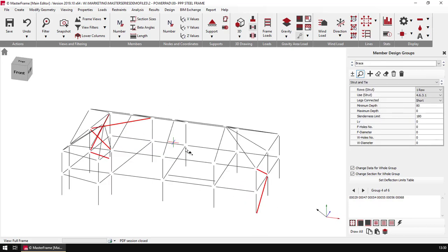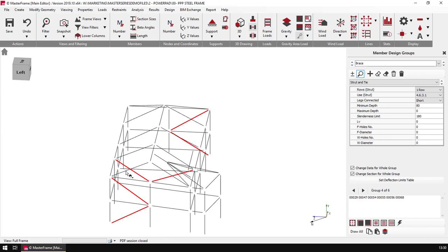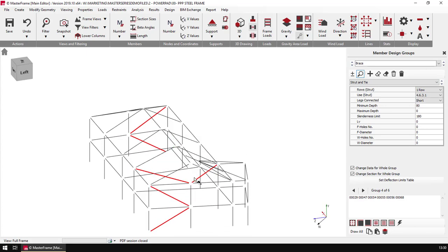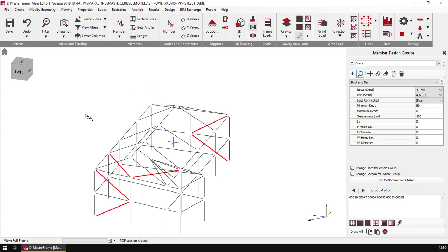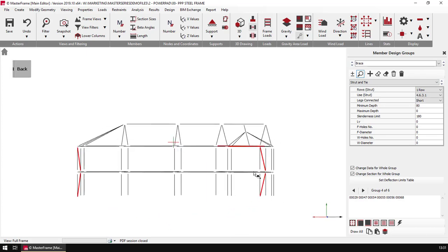Bracing is all going to be the same, including over here. We could have probably pulled that back to there and there, but I put it in as being bracing horizontally there because the roof is going to be braced from this hip end and everything else. You're asking where's the bracing in this direction?